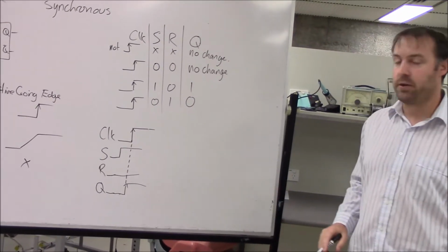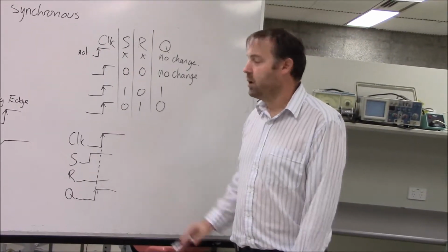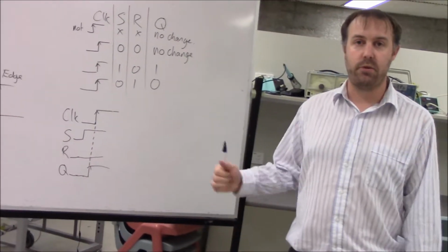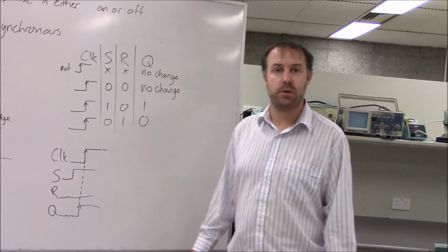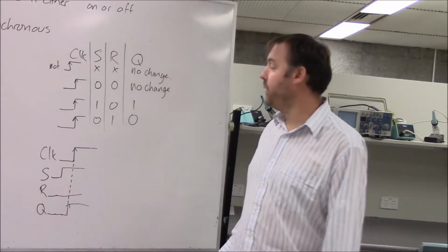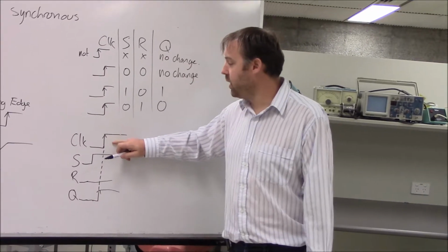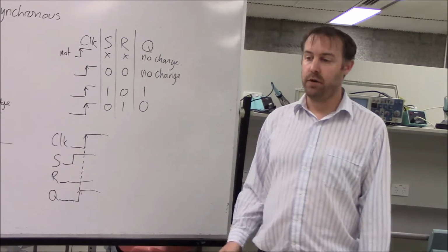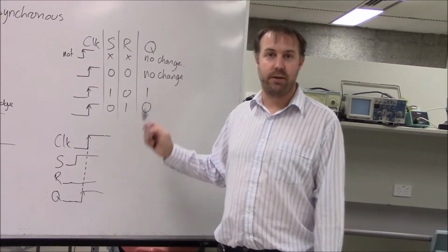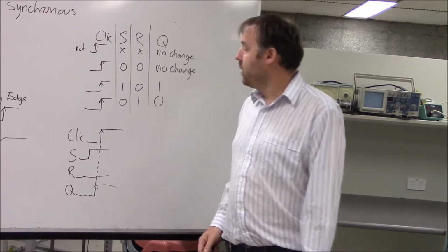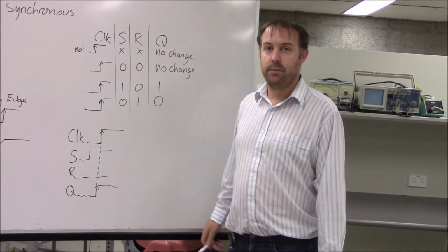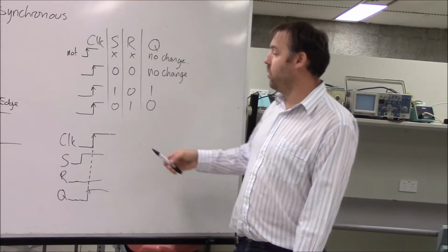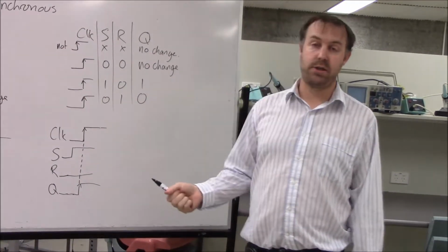And something I used to always get confused with was this clock. It doesn't have to be a regular timing thing, it could be manually driven by a switch of some sort or a sensor. So the clock here could be as irregular as you like. Could be, you know, 5 now and then 1 in 10 minutes and then 1 in 20 minutes after that. So you could have the controlling method as either yourself or a 555 timer, or triple fives, or what you've explained before, or a switch.